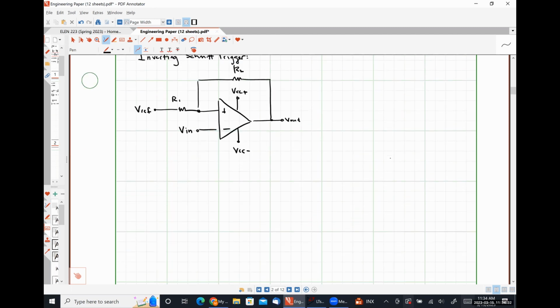And then our relationship is going to be Vn equals R2 over R1 plus R2 times Vref plus R1 over R1 plus R2 times Vout.